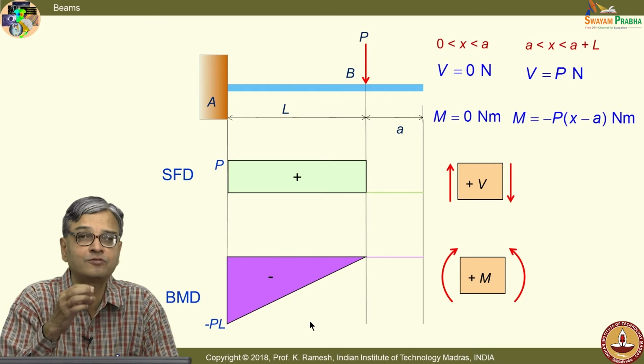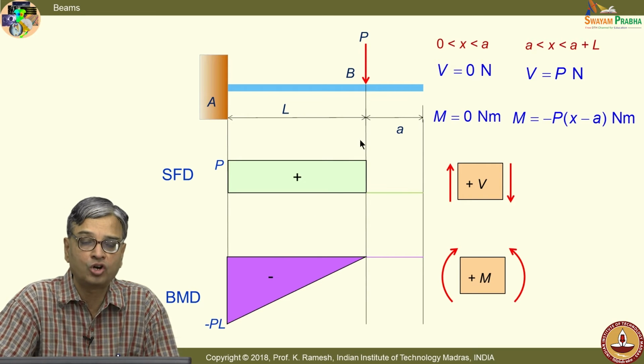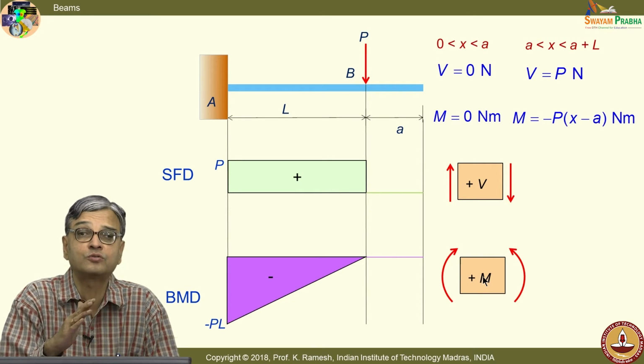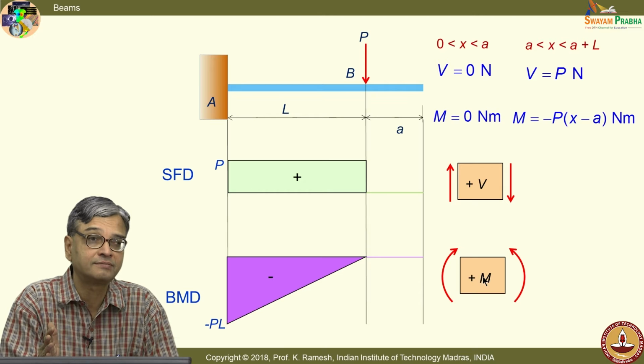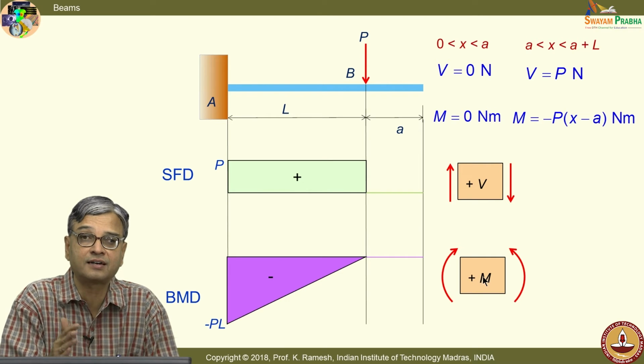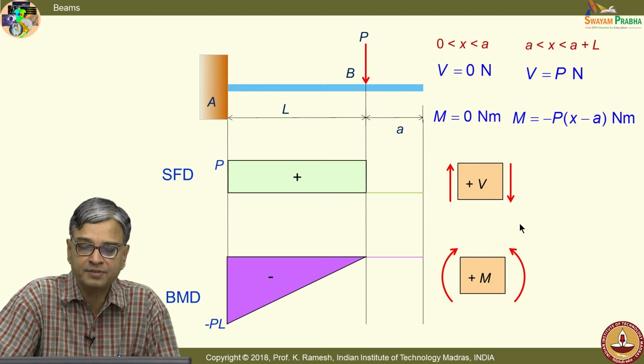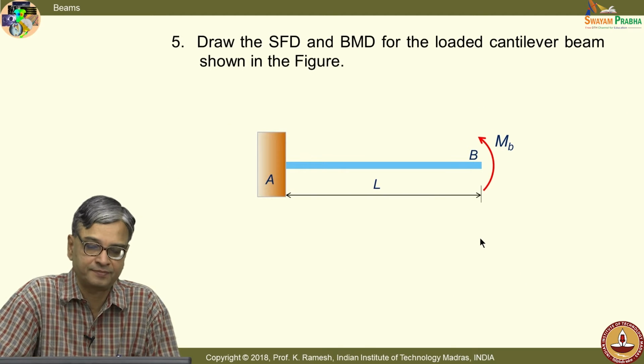So, it is always a good practice: draw the loading diagram, shear force diagram and bending moment diagram one below the other and always put the sign convention. Even if some books do not follow this habit, what we discuss in the class is what I anticipate in your exams and this is a good practice.